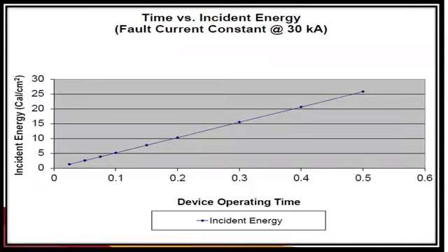And in case any incident happens and the person did not know about this factor, he will be seriously burned or seriously injured in that arc flash accident. So that's why it is very important, and now it has become part of the requirement of 70E, that you should carry out those maintenance requirements in order to check whether the device is opening and operating at the time for which it was designed, and the risk assessment was performed.